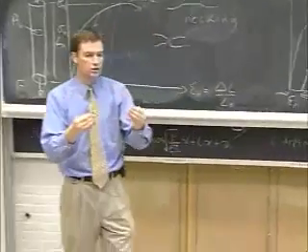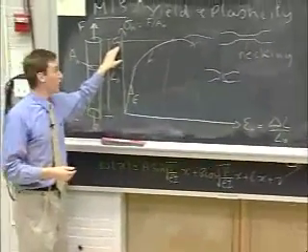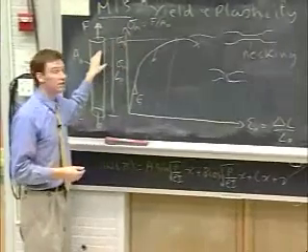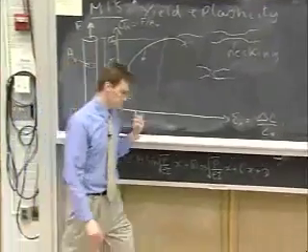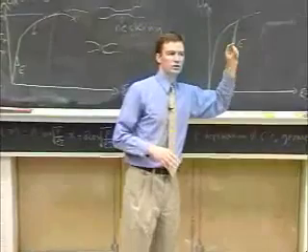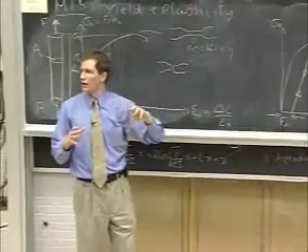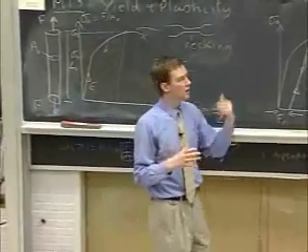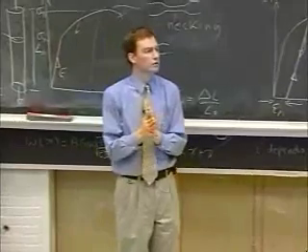The area is increasing, so if I had this behavior, the load I have to carry is continually increasing only because the area is increasing. So it's not that the material is necessarily behaving any different in tension or compression, it's that the way we've defined stress and strain is no longer adequate. Why not? What's the limit on our definitions of stress and strain up to now?